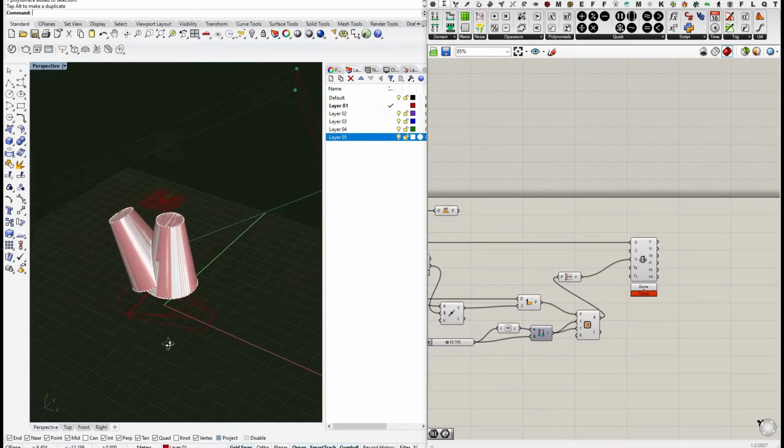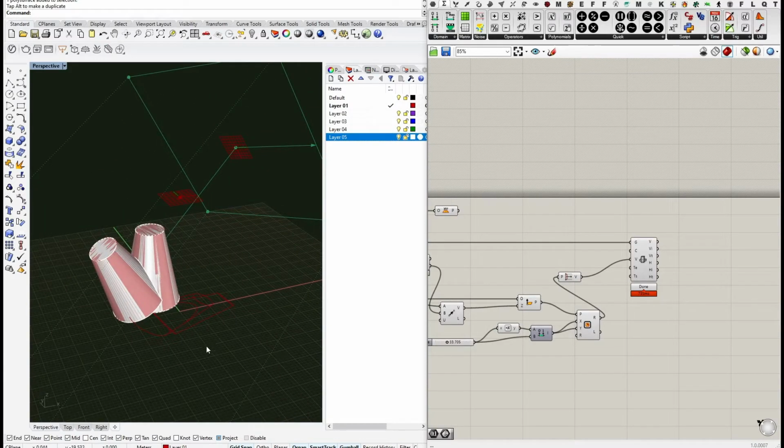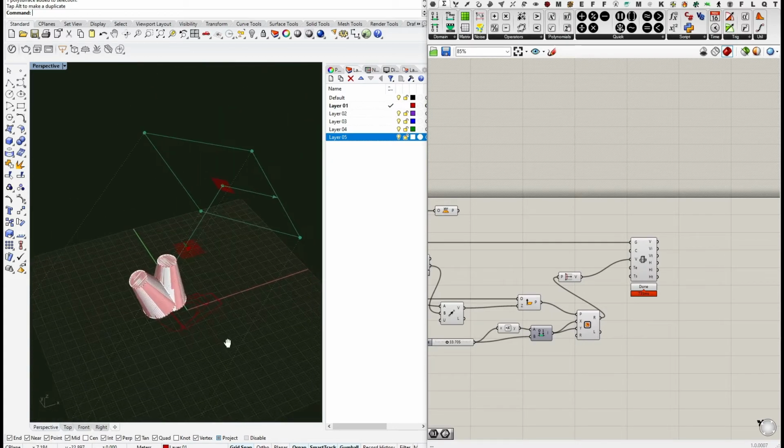If you render out an entire animated drawing, which you can have set up a timeline for it to render out over a couple minutes or hours, depending on the complexity, you will just set it up so that when you run the animation, it will run the Make2D component automatically. So while setting up, keep it in the not automatic mode, and then when you render out the animation later, we will set this to automatic so that we will automatically generate the frames.